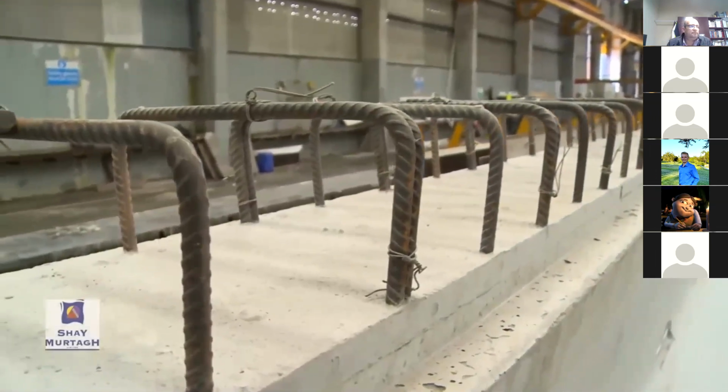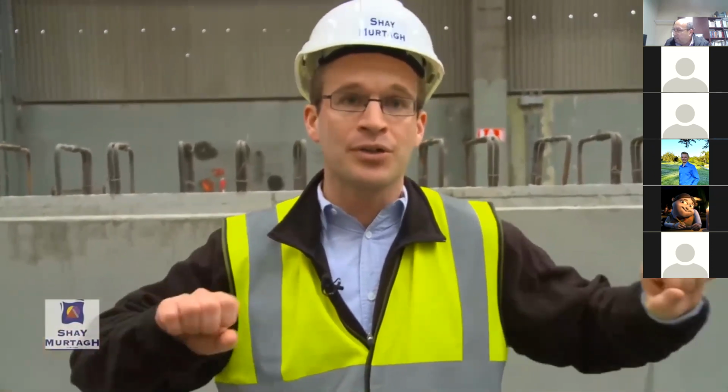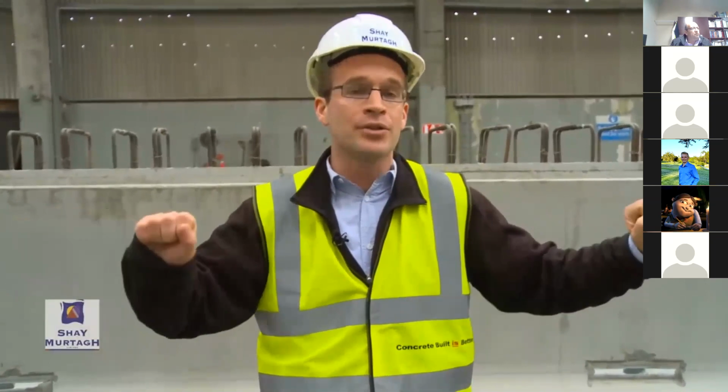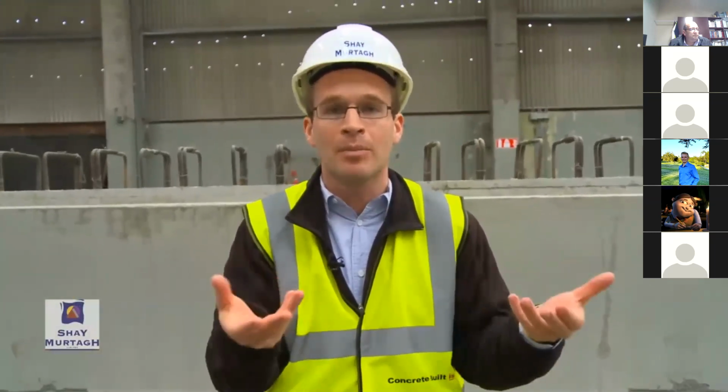So in order to summarize how pre-stressed, precast bridge beams work, beams are intended to carry flexure as well as shear, but that flexure that they're going to carry results in tension in one face of the beam. Concrete is not good in tension. In reinforced concrete, we use steel bars, but in pre-stressed concrete design, we apply compression in order to overcome that tensile stress in the beam due to flexure. The force is applied using pre-stressing strands. The pre-stressing strands are stretched. Concrete is cast around the strands, pre-tension concrete, and the strands are slowly released, thereby applying that compressive force to the beam while simultaneously applying a moment to the beam that also acts to relieve the applied moment.